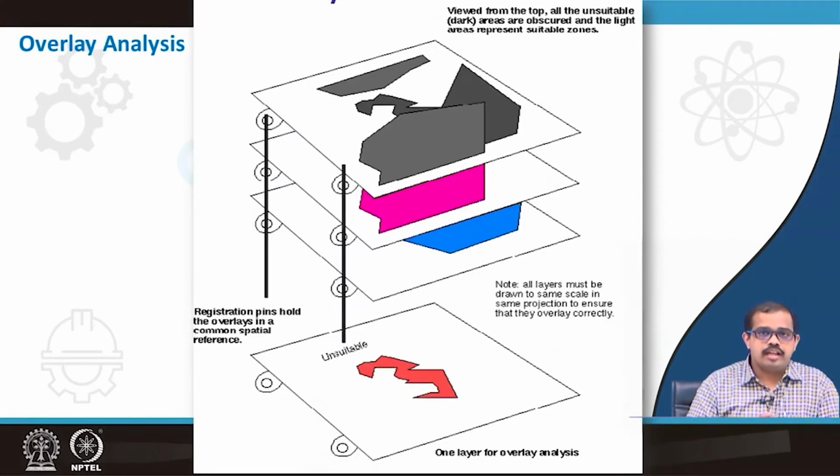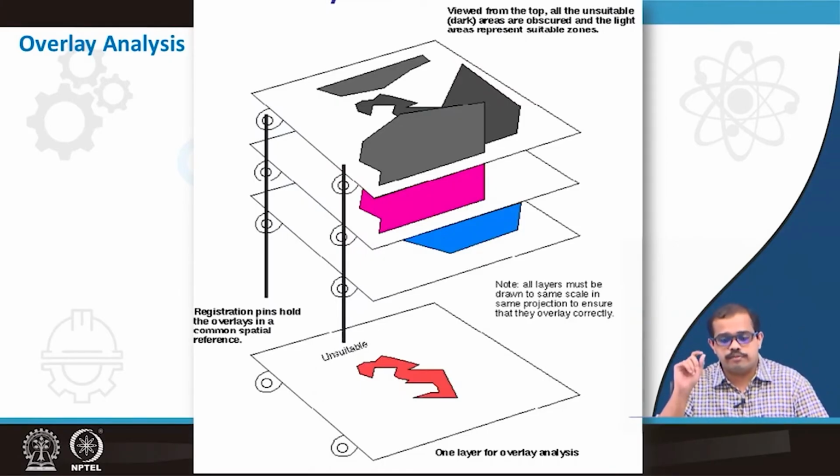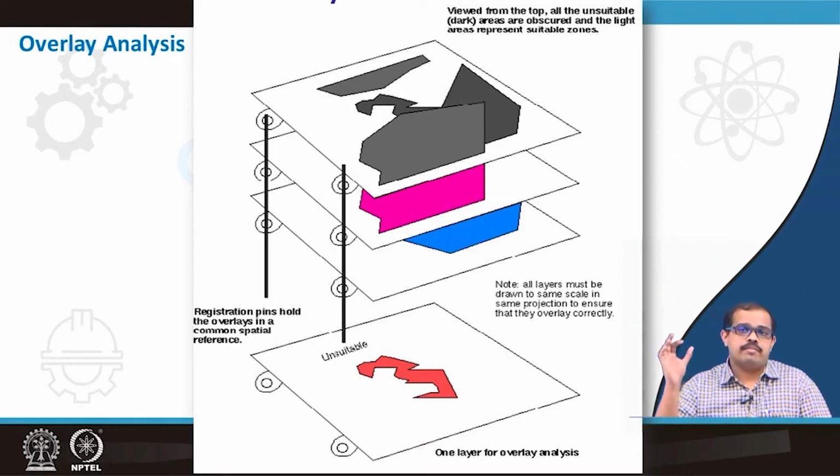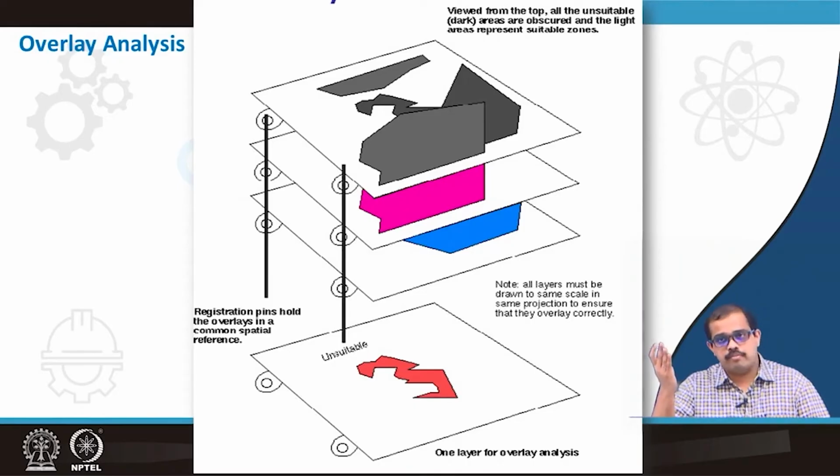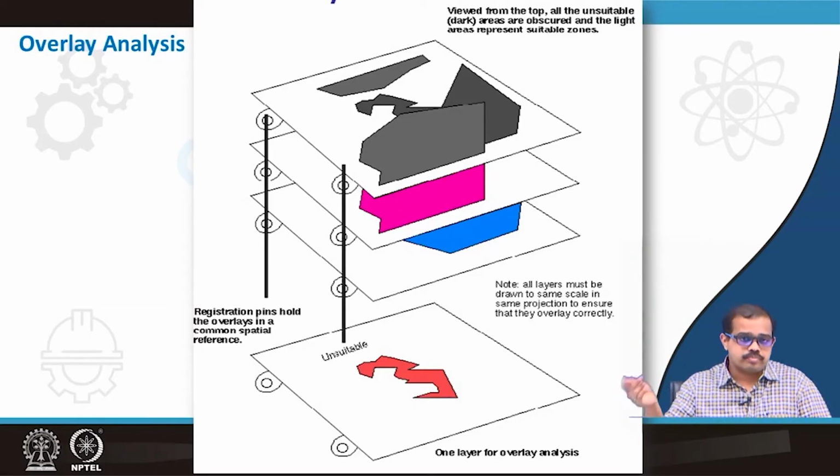And when we look at the entire overlay, for example, as I previously said, the reason I have shown you this specific image is to tell you that there may be a number of layers that you have. Let us say someone is working on urban floods. They have developed the drainage network, the urban area map from maybe 2 decades or 3 decades ago, they have digitized, they have done the classifications, whatever it may be. Then they have the ward boundaries of each of the maps, then they develop a natural drainage system, they develop the slope, the hillshade.